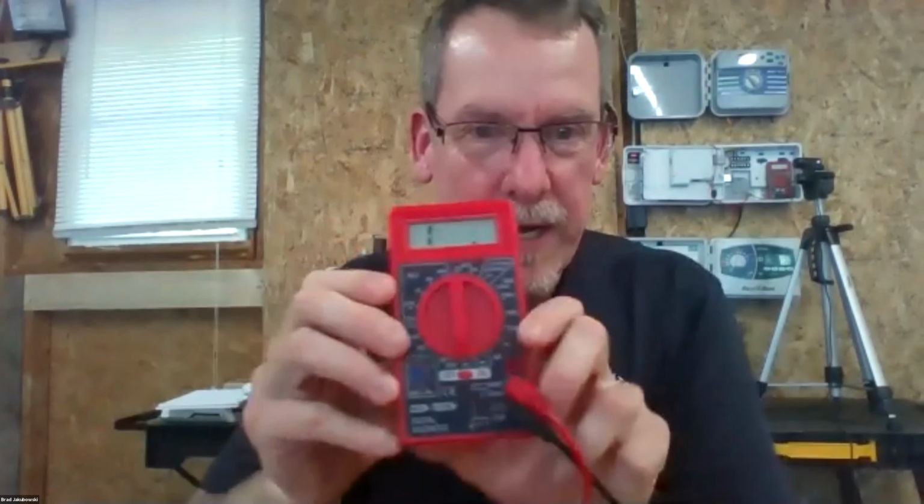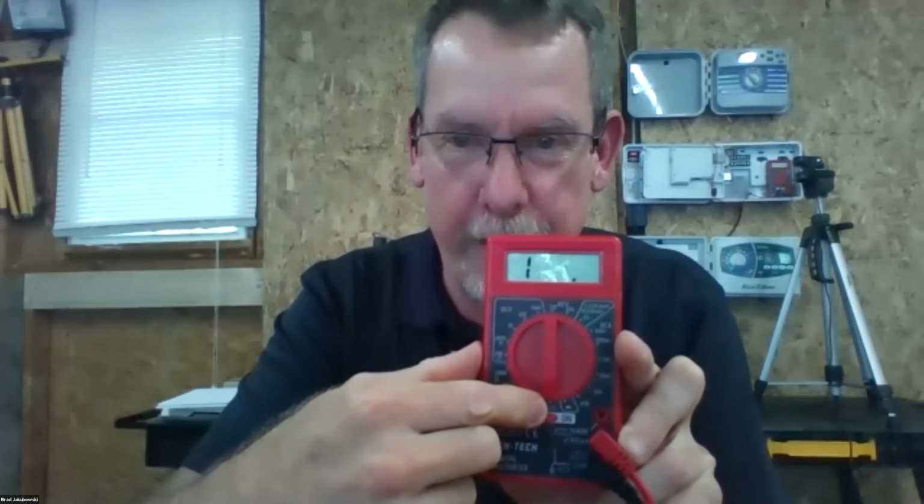And so primarily we're going to be working with ohms over here. We might tinker a little bit with DC volts here, but if we were testing to see if you're getting a signal from the controller to the solenoid, you would actually look for AC volts over here, unless it's a DC latching system that you're working with. But these are the ones that we would primarily work with when doing some of our troubleshooting. Okay, all right. So just a little bit about that.